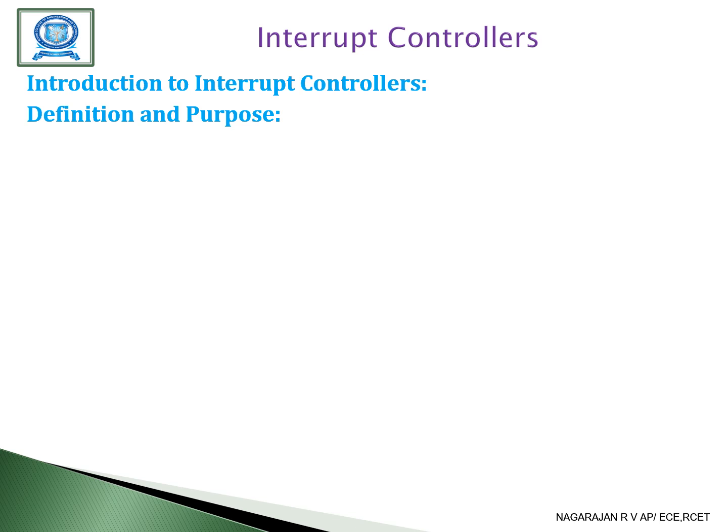An interrupt controller is a hardware module that manages interrupt signals from various peripherals and directs them to the central processing unit. It prioritizes interrupts, handles multiple interrupt sources, and ensures that critical events are promptly addressed by the processor. Interrupt controllers are essential in embedded systems to manage asynchronous events, ensuring that the system can respond quickly to real-time requirements while maintaining efficient operation.